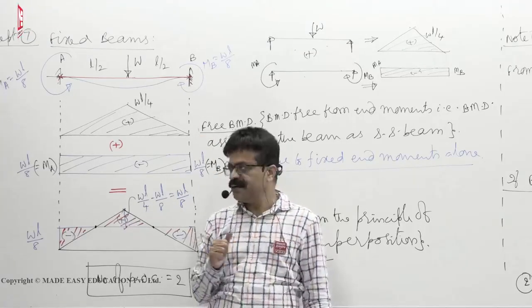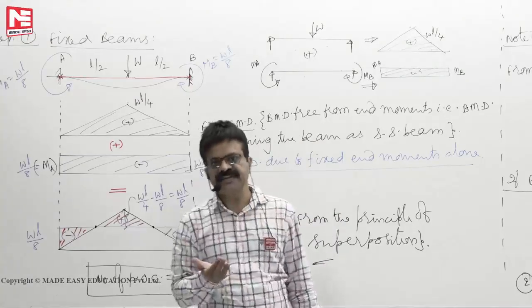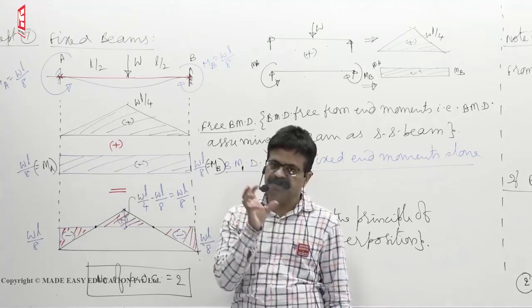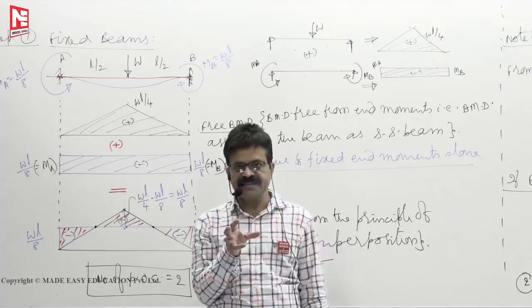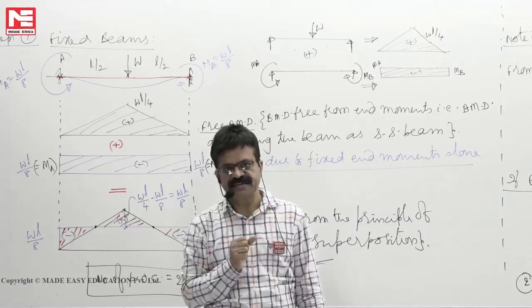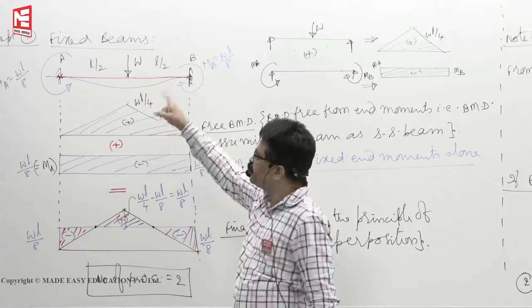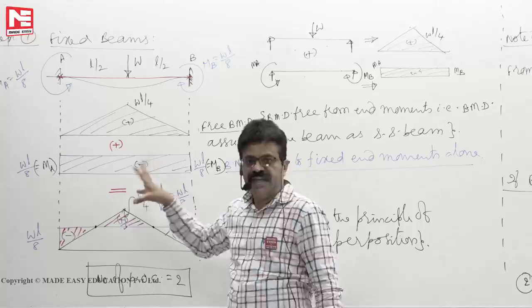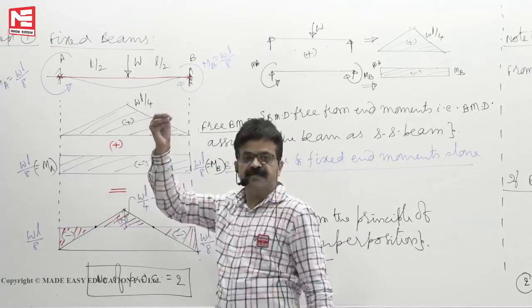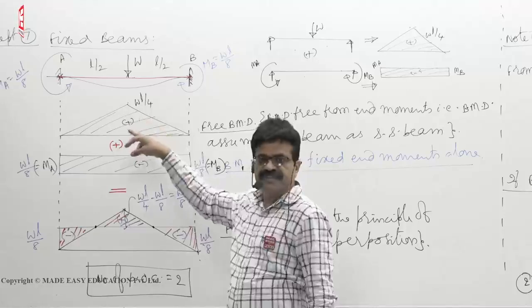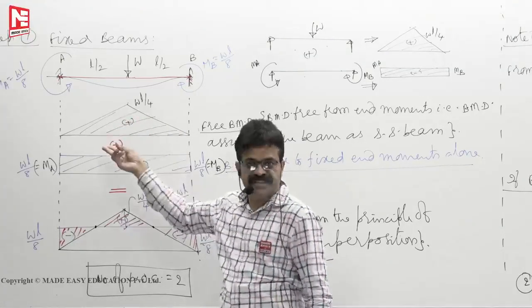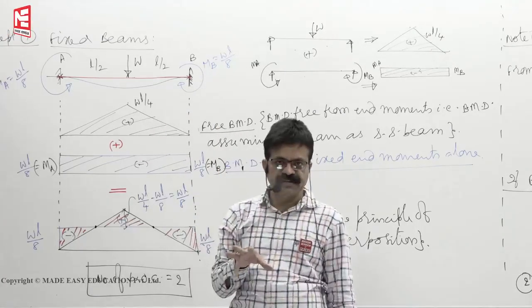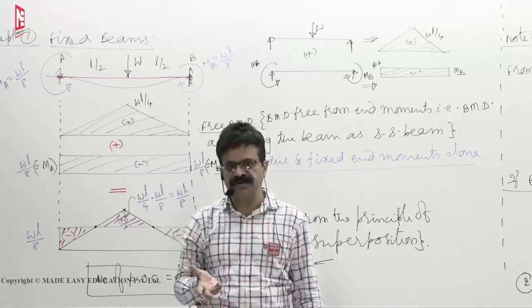That is one analysis. Now, later on in the design of steel structures, that is based on plastic analysis. The aim of plastic analysis is to find at what load the structure collapses. That means after elastic analysis is over, you continue to load till it completely collapses. Collapse does not mean completely breaking into pieces like a powder and falling down. Collapse of a structure implies that the structure will become unstable or a mechanism. Due to the applied load, if a mechanism forms, then the load we call the collapse load.